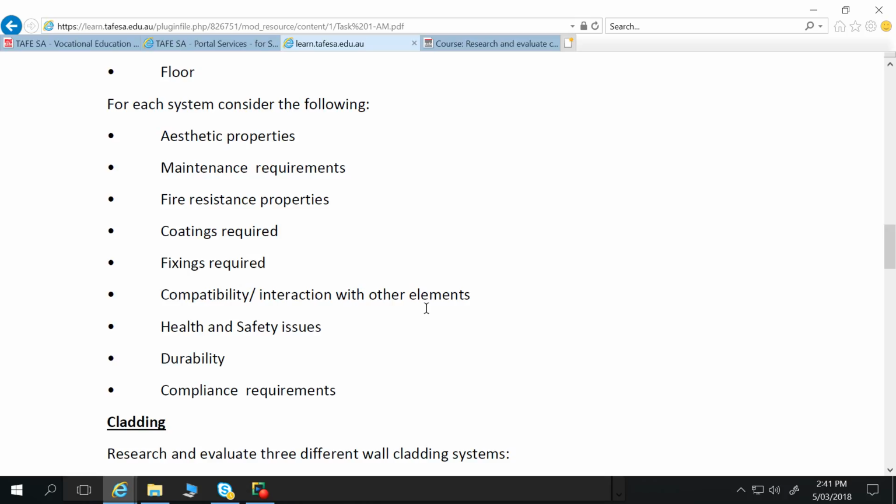A large high-rise building that was clad entirely with aluminium sandwich panel cladding, which is a very thin layer of aluminium and then about 3 millimetres of polyethylene filling. So polyethylene is a hydrocarbon. It's flammable. It's not highly flammable until it gets hot. When it gets hot, it starts off-gassing, becomes flammable, and then you've got another sheet of aluminium. Once again, let's say it's like 0.6 millimetres. So the whole thing is about 4 millimetres thick.